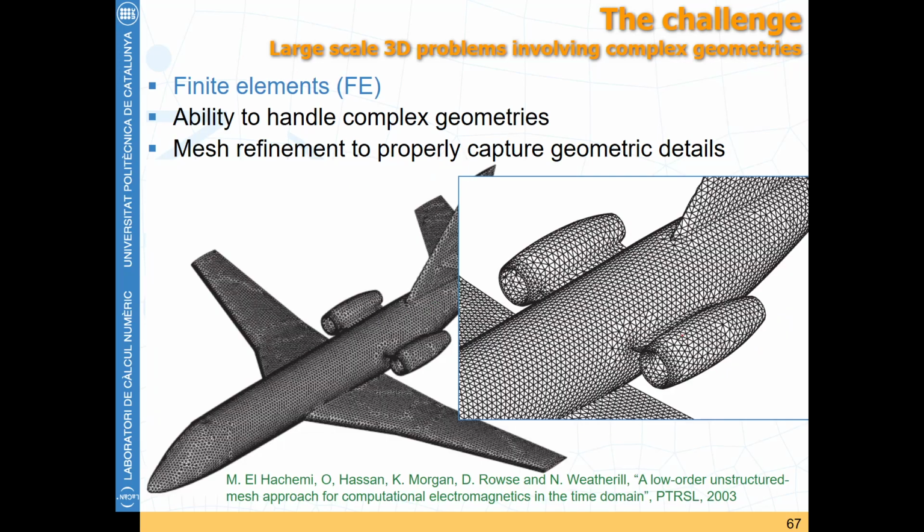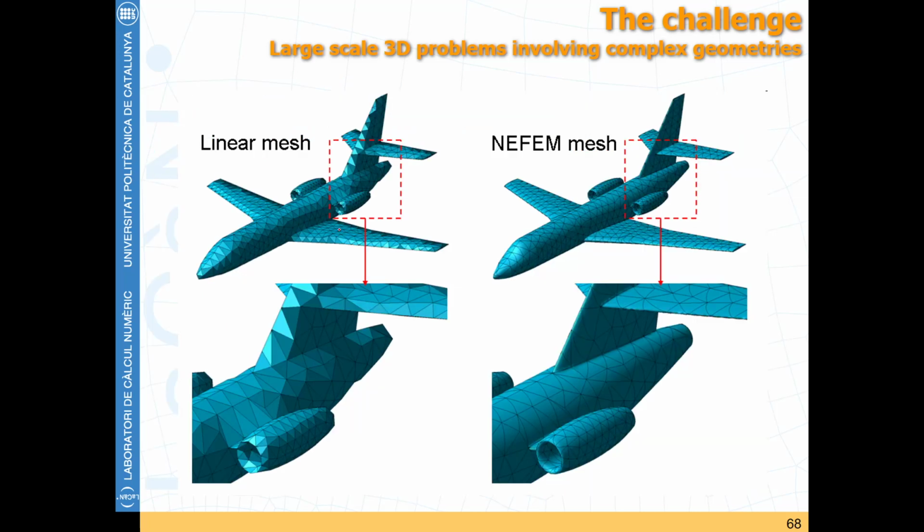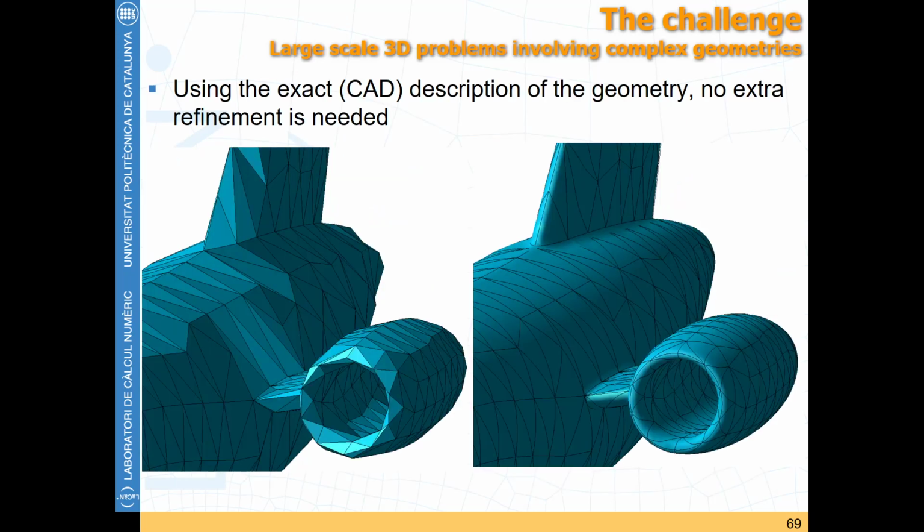And of course, because of your boundary, you can also use a smooth surface description, like here. The difference is that finite elements are piecewise linear, whereas instead you can work with piecewise higher degree, and you can impose even continuity. I'm working with C1 elements, and that of course has an effect on your actual solutions. So this is still a challenge. There are people working on the meshes, because what the CAD people have is a mesh of the surface, but of course they don't have a mesh of the 3D domain.